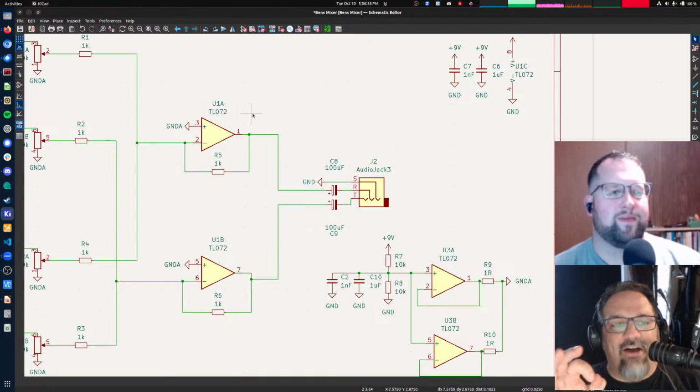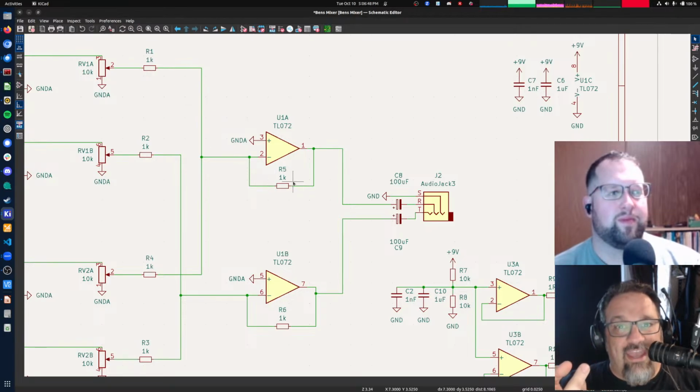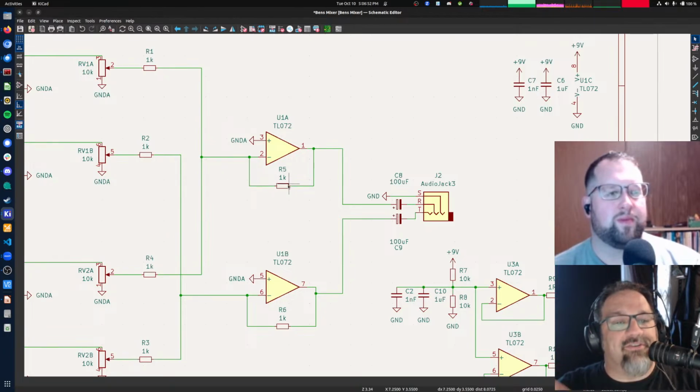So just start out with the two simple cases of just an amplifier. You look at how these resistors compare to each other, and that can give you gain. We have it so that the resistors are the same, so that's called unity gain. The gain is 1. So the output voltage will be exactly the same as the input voltage, the way we have it configured here.